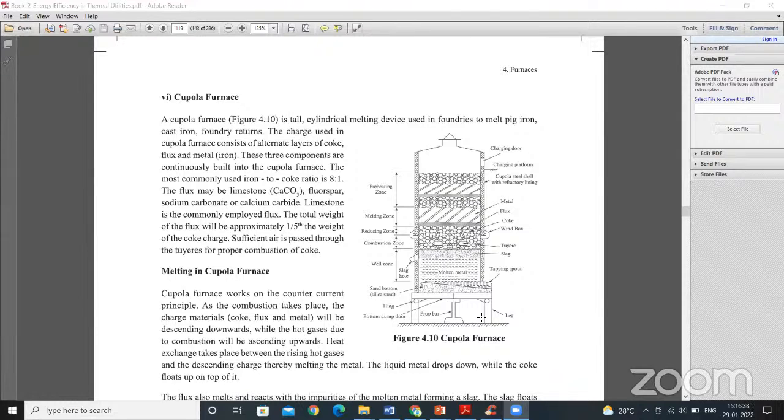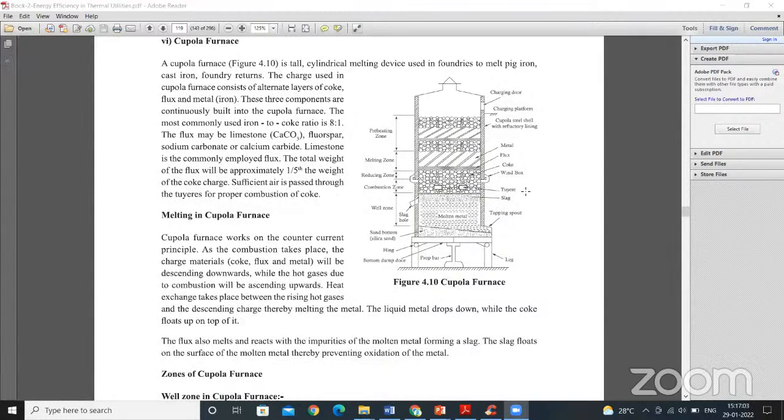We sometimes need coke to fill inside the furnace, and the preparation work before commencing the firing is also higher, and the installation failure rate is also very high because of the furnace heat transferring capacity. That is why the cupola furnace was earlier replaced with an electrical furnace.